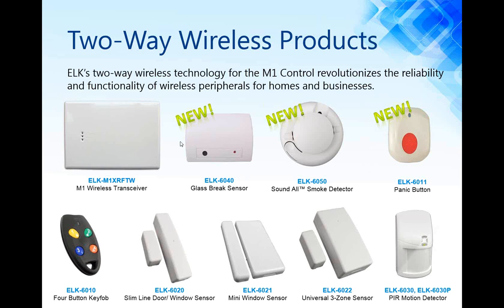If you have a large area you need to cover using wireless sensors, you can add additional wireless transceivers to the data bus to help increase the coverage area or to eliminate any dead spots that you might have. You can have up to 4 ELK wireless transceivers on the M1 data bus. The M1 will support up to 144 wireless zones. Out of the total 208, 144 of those can be wireless.